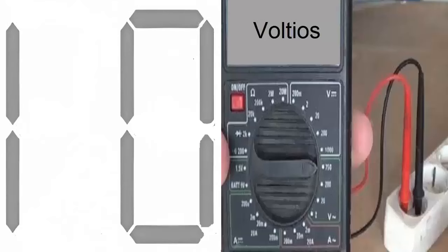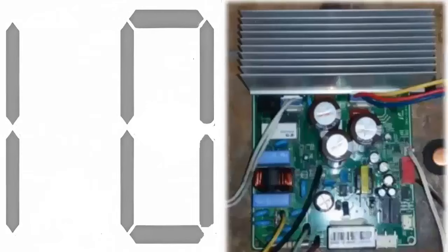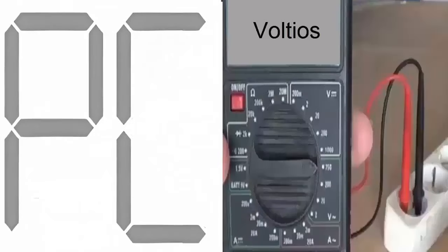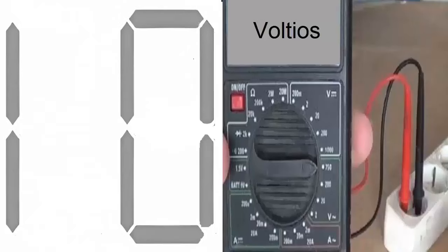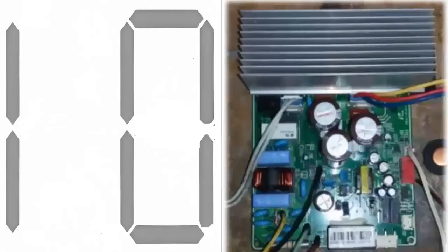The error code PC10 in air conditioning systems, for most brands, indicates an anomaly in the voltage supplying the outdoor unit, known as the condenser in cooling mode. The error code PC10 is generally displayed due to low voltage protection. This means that the air conditioner is receiving a voltage lower than normal, which can put its internal components at risk.